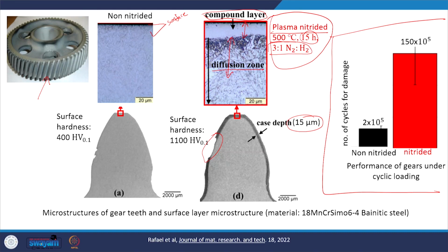Suppose I give you a bending wire which we use regularly. If I want to break this wire by pulling it, it will not be possible for me, right. But if I bend it this way, this is called cyclic loading, and it can break, right. Very often you see that when people are using these kinds of wires, they use such kinds of processes.